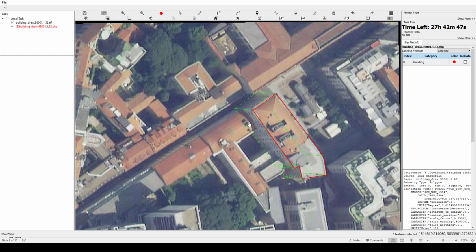The next part is the trace tool. I'm going to draw this part here in relation to this building here. They need to have the same sidewalls, obviously different height but the same sidewalls. So I'm going to use H. It's going to copy the properties of this building here. And then since it's H, I could shift to F. So it's right angled. See that?